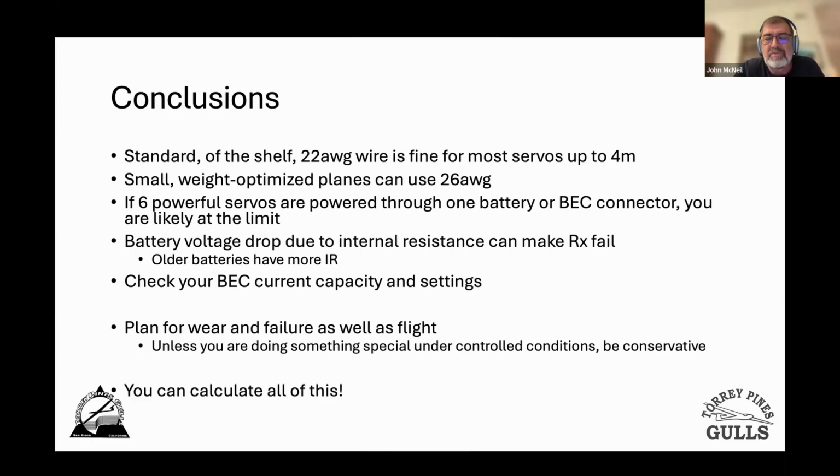This battery drop thing is real. Short circuits and broken wires are a good way to lose a plane. Battery drop from internal resistance is a good way to lose a plane. If you're using a BEC, whether it's a standalone one or part of an ESC, read the manual, check the settings, make sure they're what you want them to be. And I've said it 1,000 times,